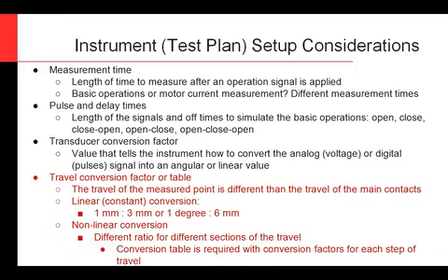And so now you might have a rotary measurement where the first 1 to 10 degrees, it's 1 millimeter per degree, and then 10 to 15 degrees, it's 2 millimeters, and then it's 1 millimeter again or whatever. So you actually need a conversion table. This is something you would have to get from the manufacturer. Sometimes they're good about providing it, sometimes they're not.